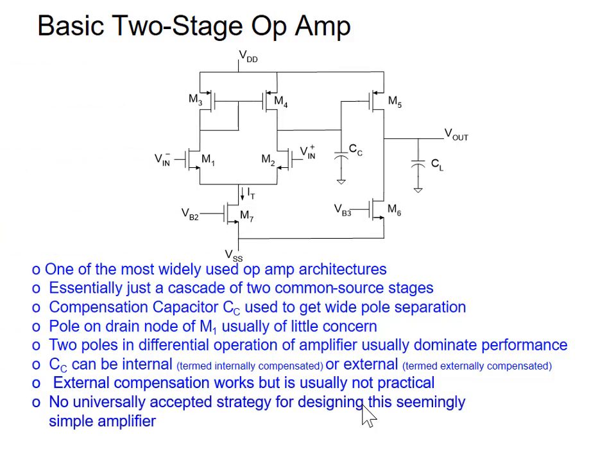You know, this structure has been talked about for 30 years. And there are quite a few degrees of freedom in this design. You've got a bias voltage here, a W over L ratio that's 2, W over L ratio 3, W over L ratio 4, W over L ratio 5, bias voltage 6, W over L ratio 7, and a compensation capacitor 8. There are 8 degrees of freedom in this design, and maybe only one constraint to make it work. And that's to pick the right size compensation capacitor so it has the right frequency response. At least 7 degrees of freedom.